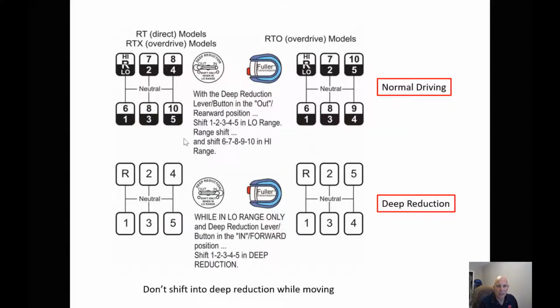And again, one of the ones we talked about earlier was deep reduction. Now in the deep reduction, if we put the deep reduction in, we can't split the gears. So it's only when the deep reduction is out that we're allowed to split the gears. And again, it may vary between models, so we need to know how the configuration is set up.